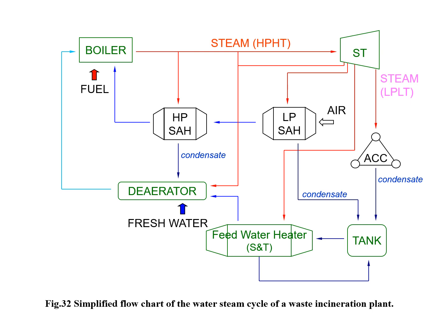Low pressure and low temperature steam exhaust from the turbine is completely condensed in the air-cooled condenser. Condensate from the steam air heater and air-cooled condenser is mainly collected in a drain tank. In a feed water heater, recycled condensate is preheated by steam extracted from the turbine, and then oxygen is removed in the deaerator.